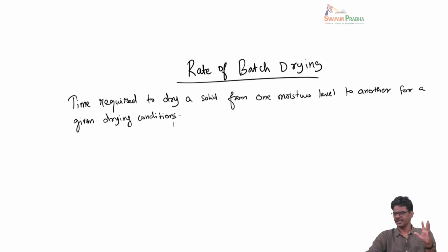Okay, let's say for an industrial scale you have a large amount of material you want to dry. What you do, you take that material in a very small quantity and then you subject this to a lab drying test under a very similar condition that you want in an industrial setting. Okay, by matching the drying conditions in the lab scale and in industrial scale and using a very small amount of drying material, you can look at what rate the moisture is removed from this material. Okay, so this is basically a lab drying test, and then based on this lab drying test we can infer some information and we can use this information to scale up and predict what's the actual time required for a large industrial scale drying operation. Okay, so that's the strategy we are going to use.